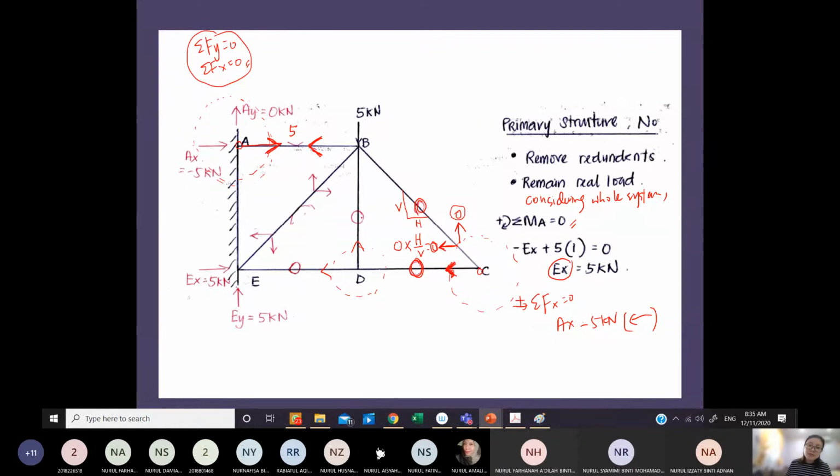So now by using summation Fy, this is also 0. And this horizontal, of course, is 0 because there are no other forces, no support reaction, no loads, no other external force that contains any value. Therefore you have left only one member force in your analysis. You can proceed with E, or you can proceed with B. So let's try B.